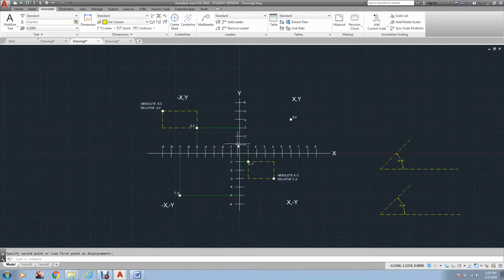Now, when using AutoCAD, just to remind you, as you see me moving around down here at the bottom are the coordinates. Again, don't worry about that third one. That's Z. That's actually more for 3D. We'll get into that later on in the advanced course. But here, you really have three different ways of using coordinates. You've got absolute coordinates. You have relative coordinates. And there's polar, but I just want to stick with the first two.